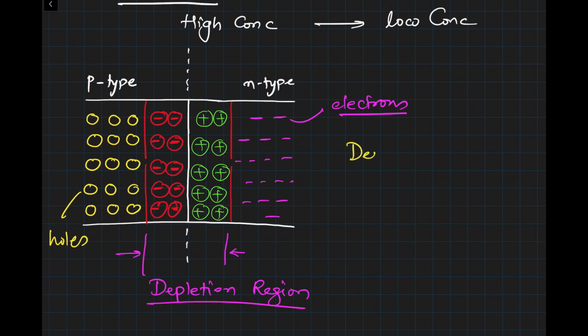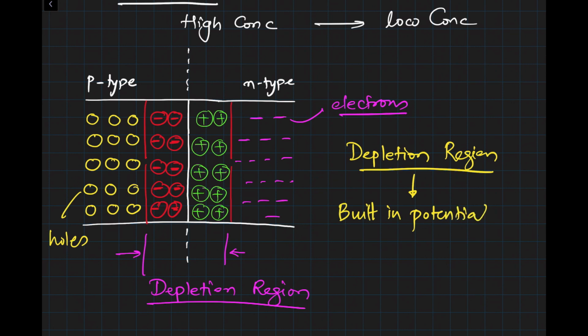So you have the depletion region, which means all the mobile charges are depleted from the interface section, and as a result of the depletion region, we have a built-in potential because of separation of charges at the junction, and we call that V0. And as soon as there is a potential difference, there will be some kind of electric field over here.